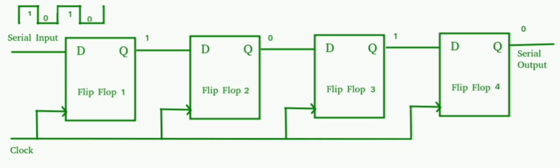Thus, finite state machines are sequential circuits whose past history can affect their future behavior in only a finite number of ways. That means finite state machines are machines with a fixed number of states. Every finite state machine has a finite number of memory devices. The block diagram of a finite state machine is shown in the figure. Here x1, x2 are the inputs, y1, y2 are the outputs, z1, z2 are the state variables, and capital Z1, capital Z2 represent the next state.